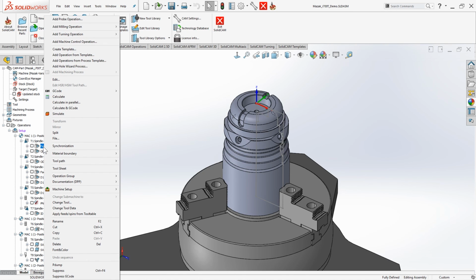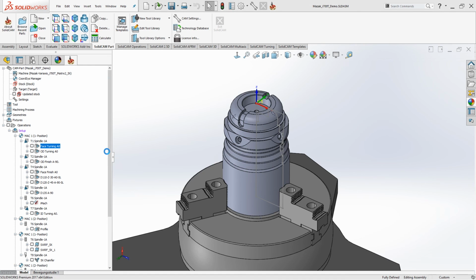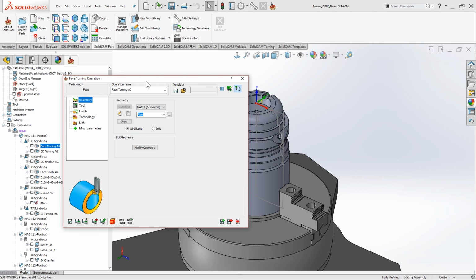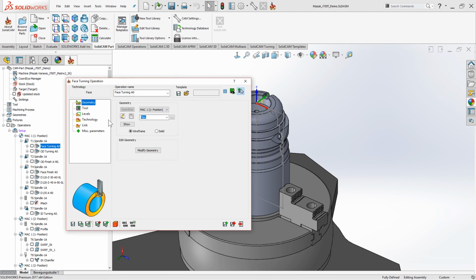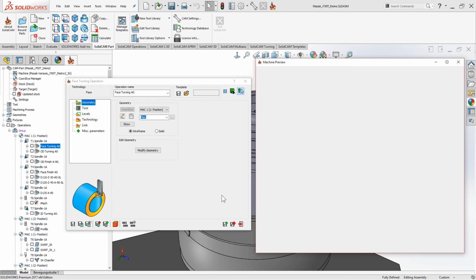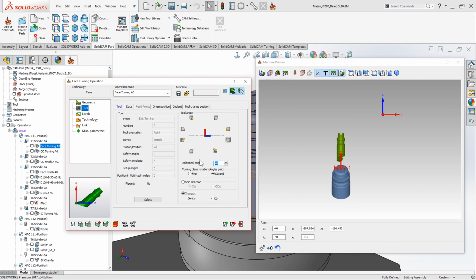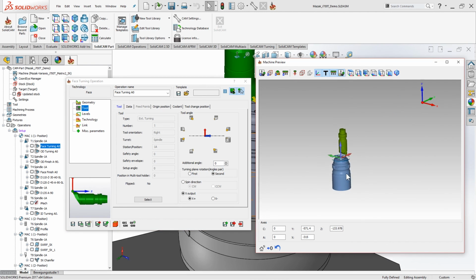And let me just show you the rules that we have applied, and how they actually affect our system. So first of all, I'll just open any random turning operation, and over here I have my machine view, so I can go there and click it, and let me go to my 0 degrees over here, and what I have here is what happens if it's A0.